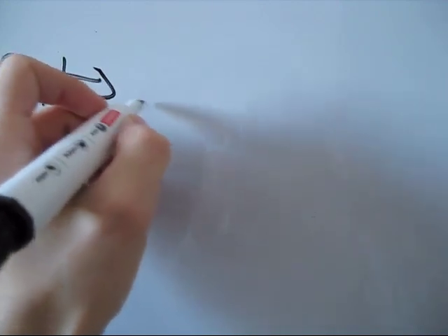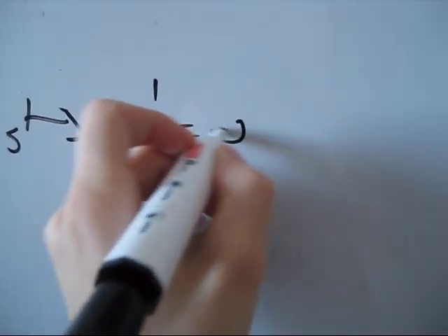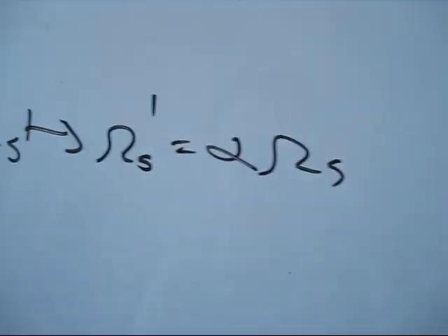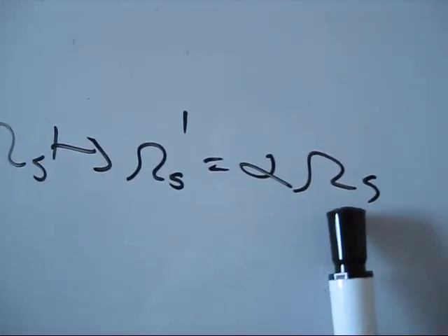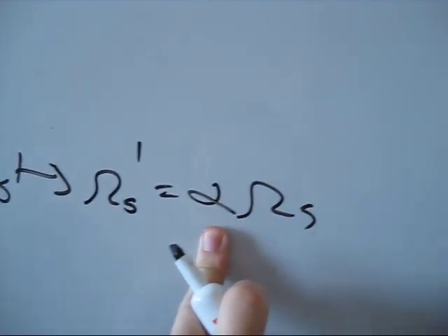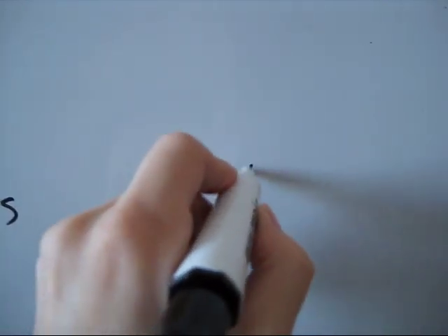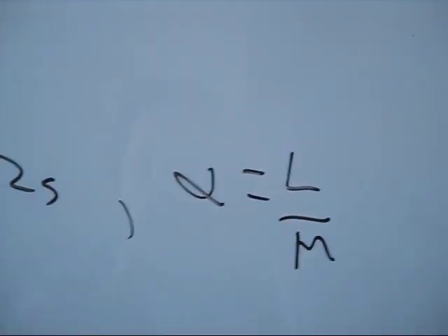It's because let's say you want to downsample at a non-integer value, right? So let's say you wanted to take your sampling frequency and you wanted to go to a new sampling frequency, where it's equal to alpha times your original, where alpha is some non-integer value. So let's say then that using the letters that we were talking about before, alpha equals L over M.